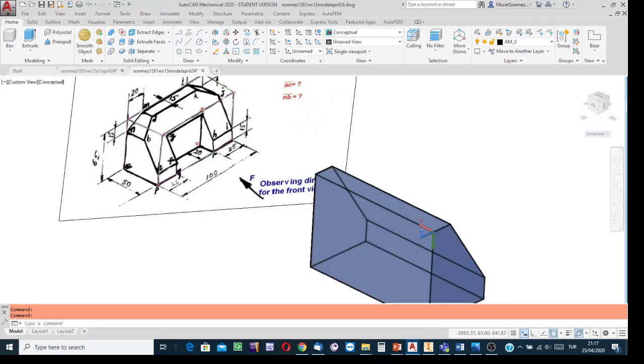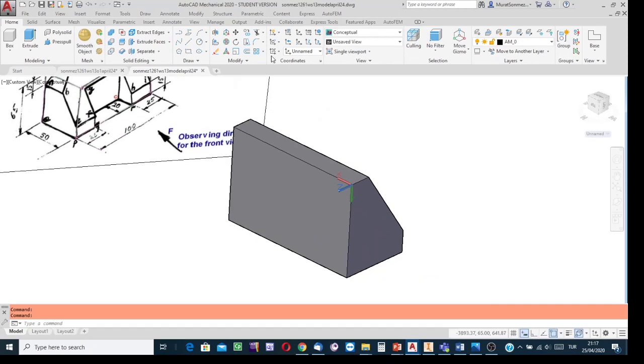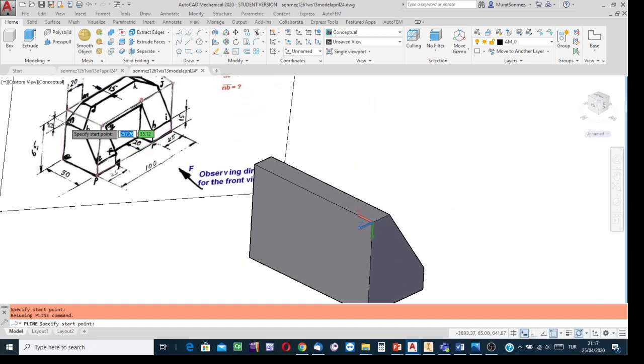So similarly, start a polyline creation process. And then I'm going to mark the lower terminal point. It corresponds to the image of NB. For this point, the abscissa is 0, write 0. Click on the comma key.